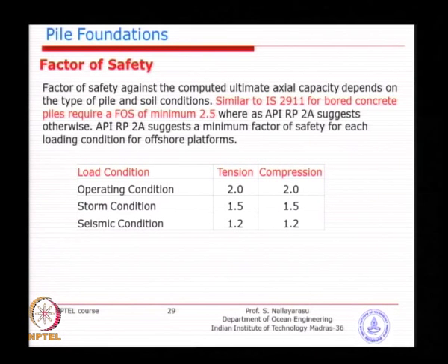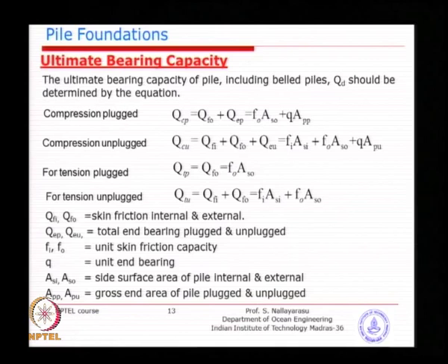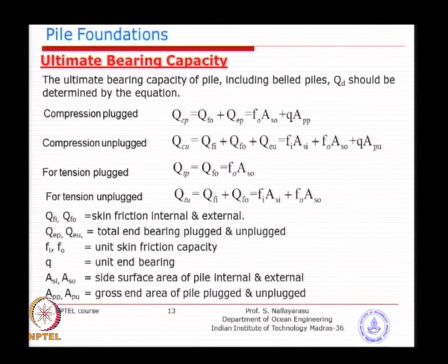So, that is why we have to look at how we cover these uncertainties, that is one parameter. The second one, all this while we were looking at the failure of the soil by shear and ultimate, that means once the soil particles are dislocated, they will behave plastically. So, it is the strength what we have evaluated here. If you go back to the equation when we were looking at a few days back, these are ultimate capacities, not the working stress methods, which I think you are familiar with from the design course. Basically, these are ultimate capacities.